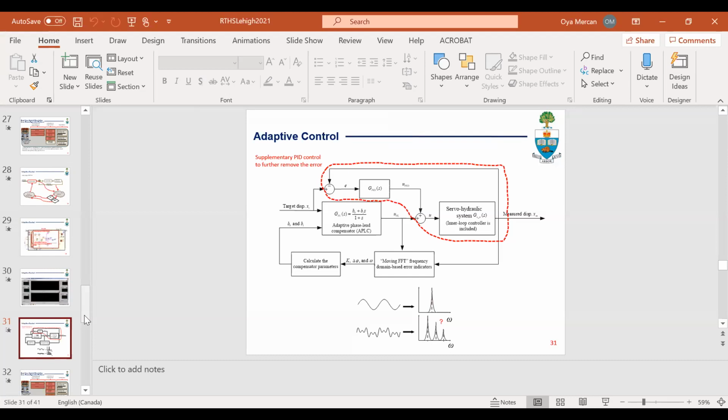There are ways to synchronize them, right? But the slowest one would govern. The question is, if you have fast enough analytical substructure state determination and a fast acting servo-hydraulic system, but they are not using the exact same time interval, when you are synchronizing the two, you can add an intermediate component which synchronizes the two.